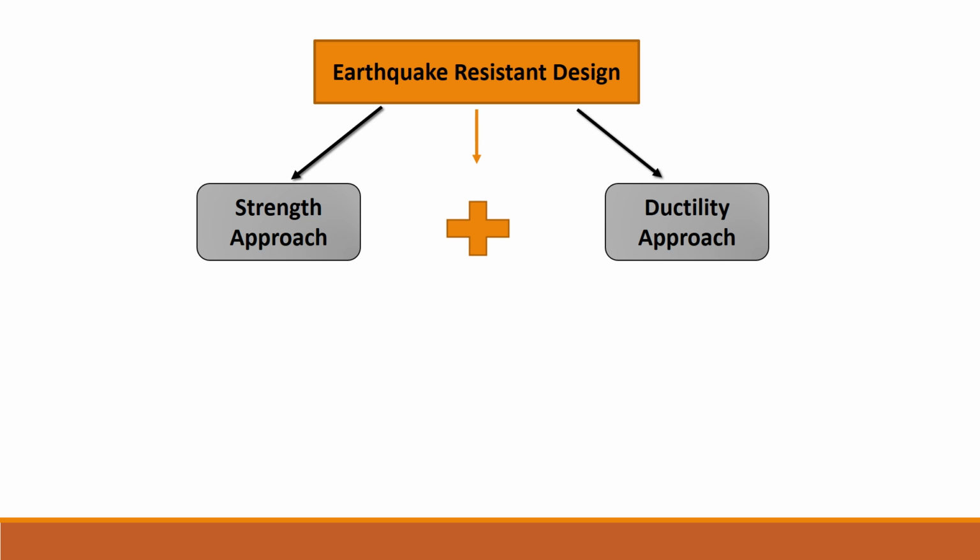We have all studied the strength approach in the classical design of structures, concrete structures. In this approach, we consider the strength of the member, which is a concrete member, to be the limiting criteria for design. For loads which are multiplied by load factors and the material strength, which is classified into the partial design strengths by dividing by partial safety factors, we obtain the strength approach.